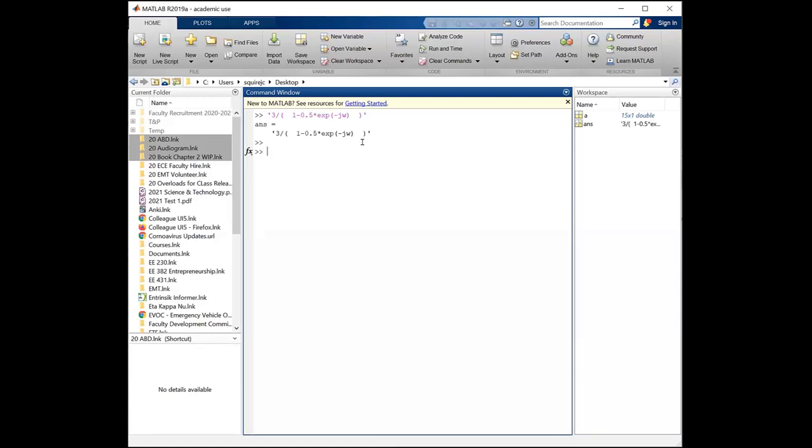So we're going to start out by, it's a function of omega, so we're going to start out by creating an omega. And I'll linspace that. Although it's unique between 0 and pi, I'm going to graph it between 0 and 2 times pi, just so you can see that folding mirrored relationship we talked about earlier. And it doesn't matter how many points we have. MATLAB will figure it out all instantaneously, so I'll give it a bunch of points.